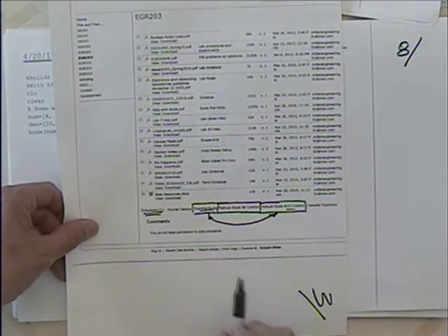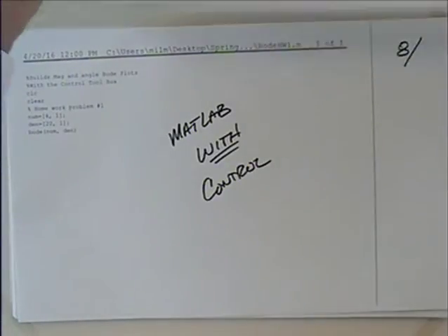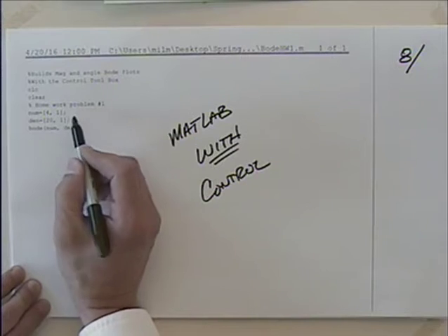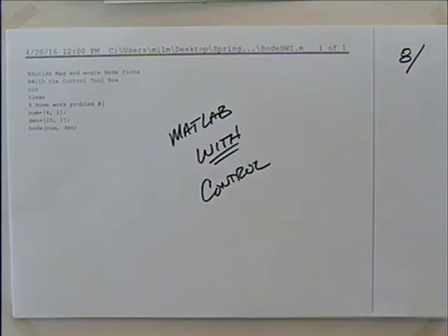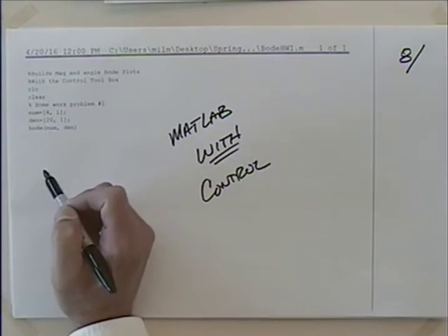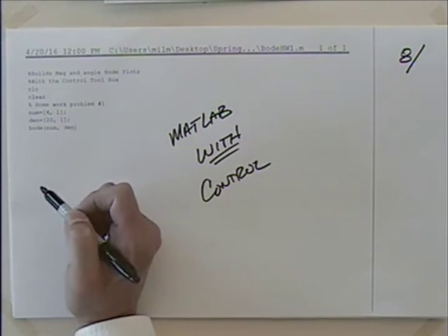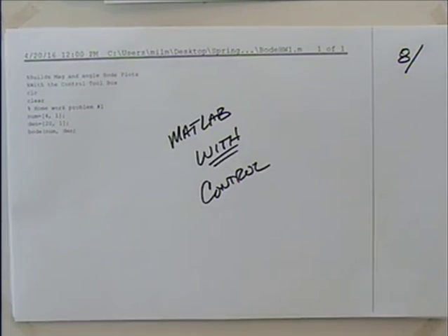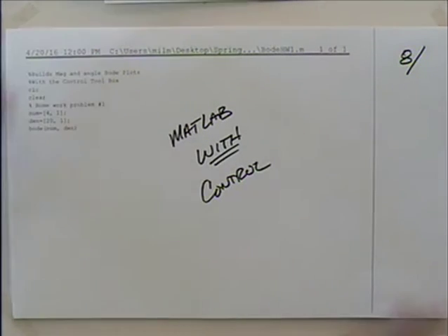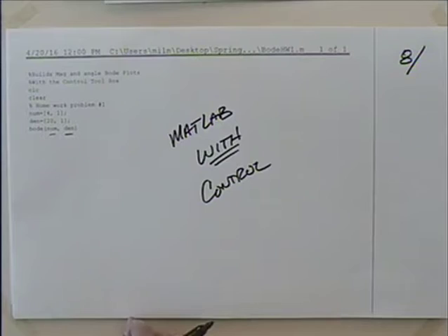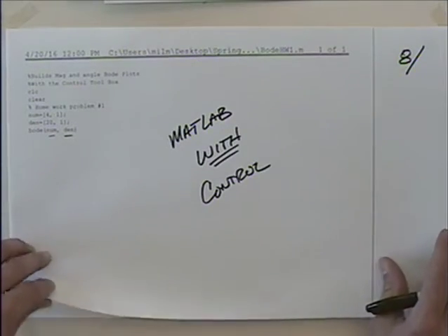Those are about the same. You've seen that. Now, Matlab with control. That's significantly different. Basically, all I do is I give the problem in terms of a polynomial. So I've got a polynomial here and a polynomial there, defined in terms of j omega and the constant. And then the Bode plot, you just have the numerator and the denominator. So a lot easier than what you've seen.